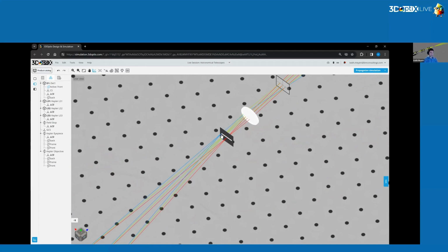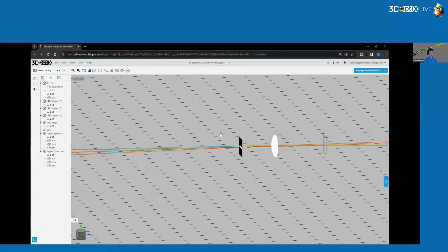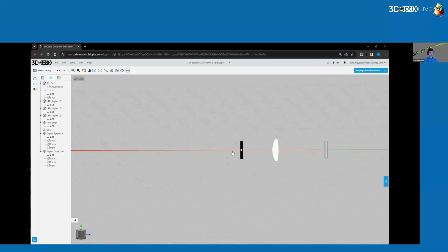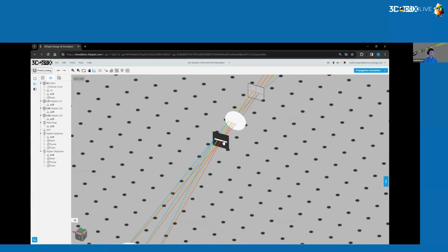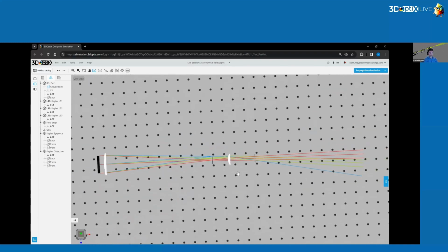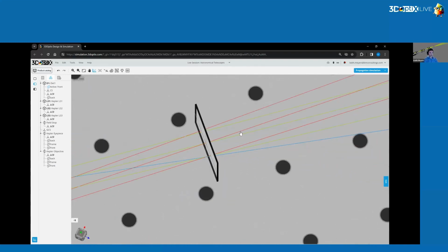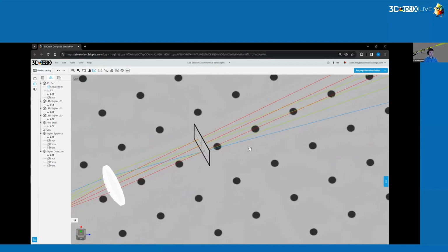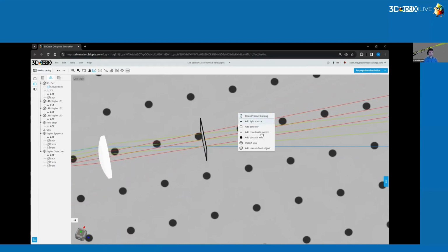And again, this is a rectangular aperture because we're using just a 2D ray fan, but we would obviously want a circular aperture if we were propagating through all the angles here. Okay, so the last thing we want to do is add our simulated eye here. The way we're going to do this is we're just going to add a paraxial lens, and we're going to put it at the location of that exit pupil. Again, this will allow us to see the entire field of view here.